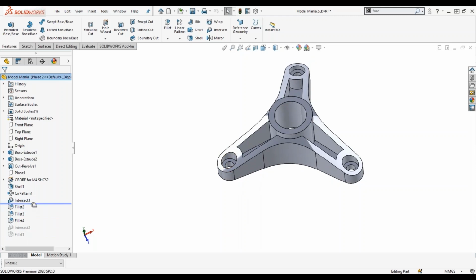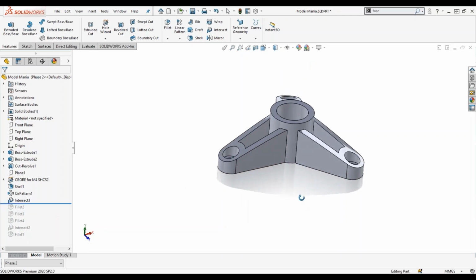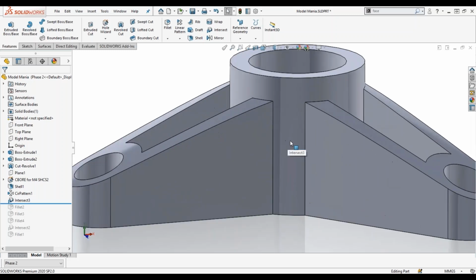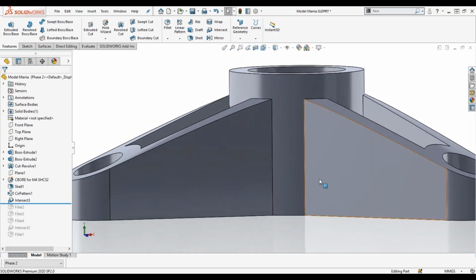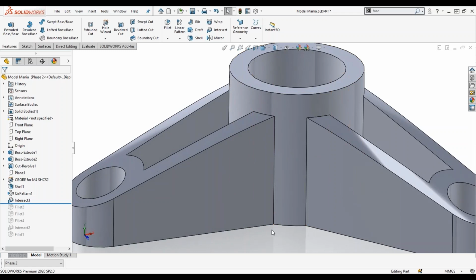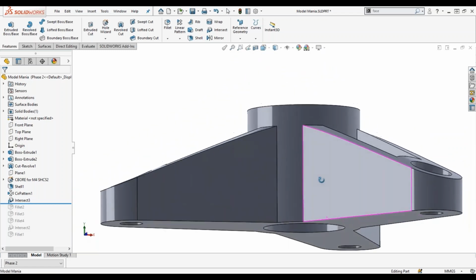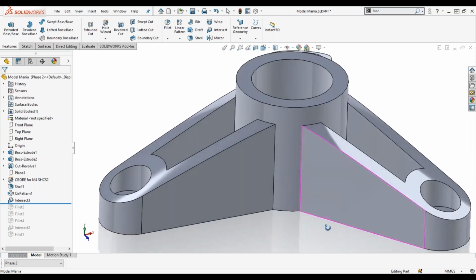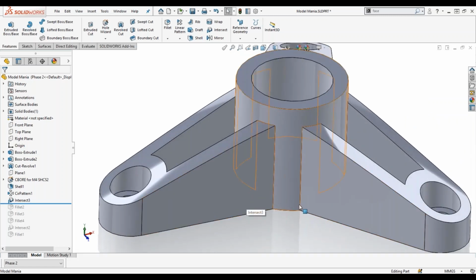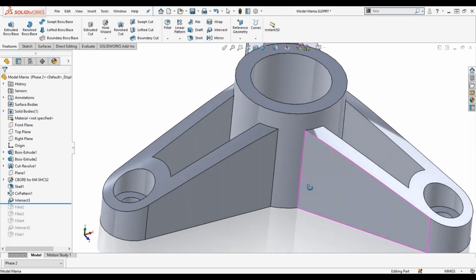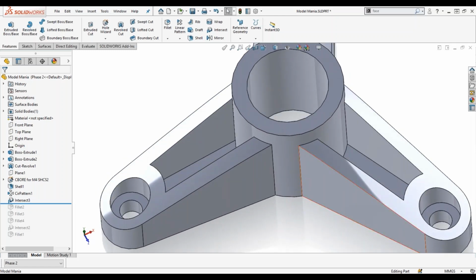Oops. Looks like this. And you're left with this kind of crappy area right here. And in order to accommodate that, with a normal fillet, it would be kind of annoying. And without a face fillet, you'd probably have to actually model the fillet into it. I don't really know of another way to get a 30 millimeter fillet right there. But thankfully there is face fillet.